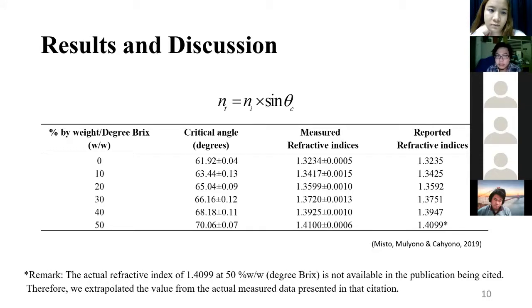Have you tried to study something similar to this, like the surface plasmon resonance sensor that people use to measure refractive indices as well? Have you heard of it? Yes, it's similar to SPR. Yes. People use that to measure refractive index, giving a higher sensitivity than times 10 to the minus 3 RIU. People have achieved 10 to the minus 5 to 10 to the minus 8 RIU, which is more sensitive. Okay, if you carry on with this, I suggest you explore that option as well.